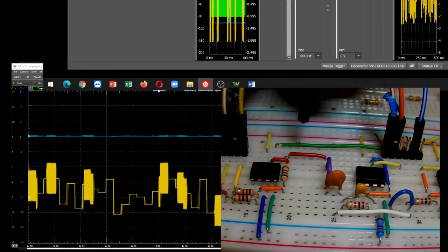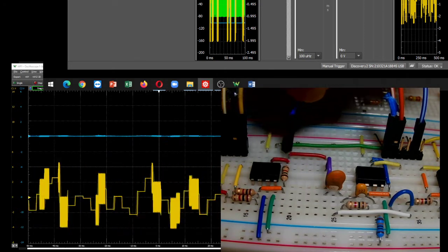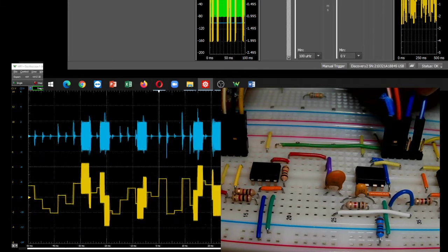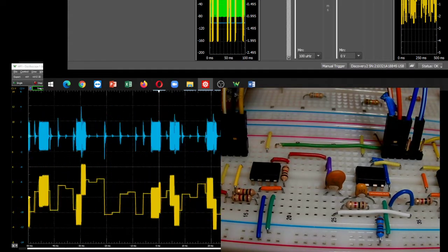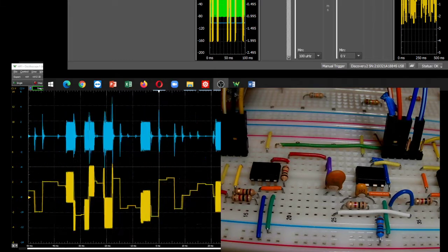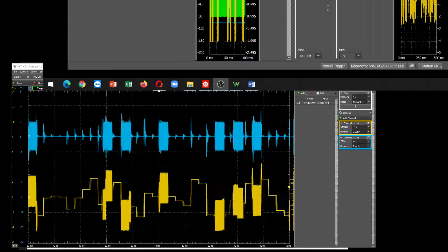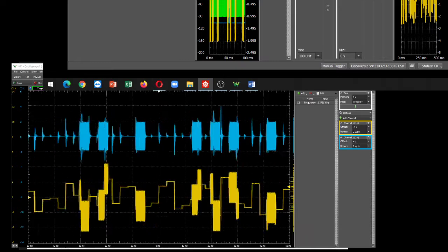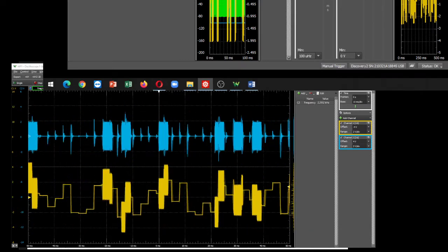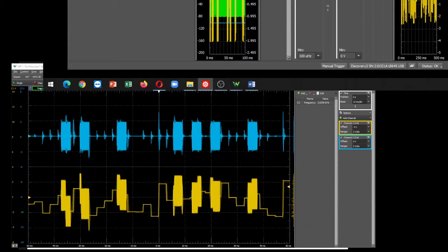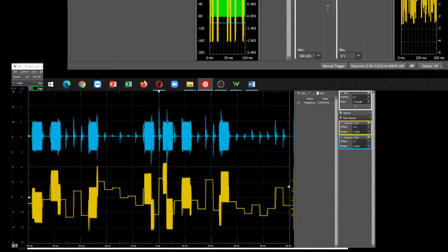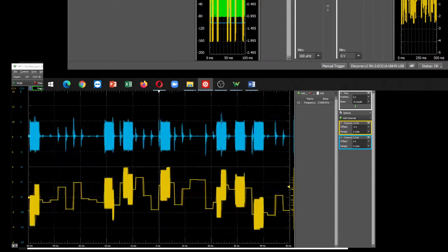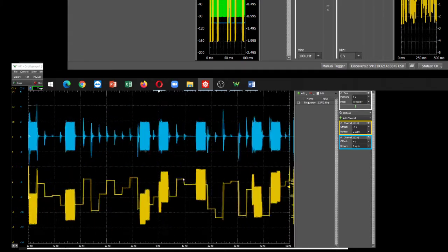The noisy transmitted signal from the left side adder circuit is input into the high-pass filter circuit on the right-hand side. The output from the filter circuit is shown next. The output of the high-pass filter circuit, top, blue, shows that the vertical random up and down of the added noise is largely gone. There remain little spikes here and there, but they are clearly distinguishable from the filtered signals, of which the key characteristic is the unmistakable high-frequency modulation over the duration of a 1-bit pulse.